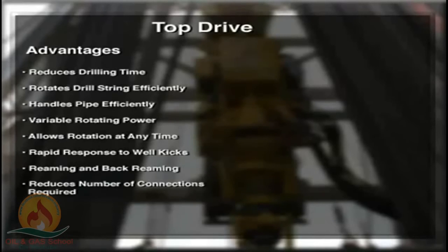If the crew can make up 3-joint stands of pipe before drilling starts, a top drive can drill triple stands instead of just 1 joint, as is necessary on a Kelly drive rig. Making up 3-joint stands reduces the number of connections required to 1/3.